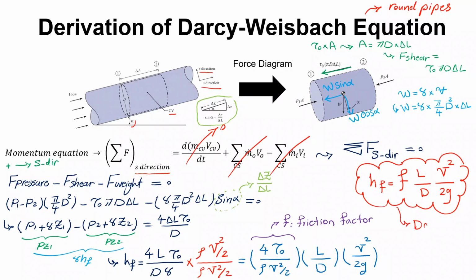This equation that I have written in red with my red pen is called the Darcy-Weisbach equation. And it can be used for both laminar and turbulent flow to calculate head loss. Now, we know about this equation. We need to find out how to calculate F, or friction factor, for different classifications of flow, and that would be the topic that I'm going to discuss from now on.